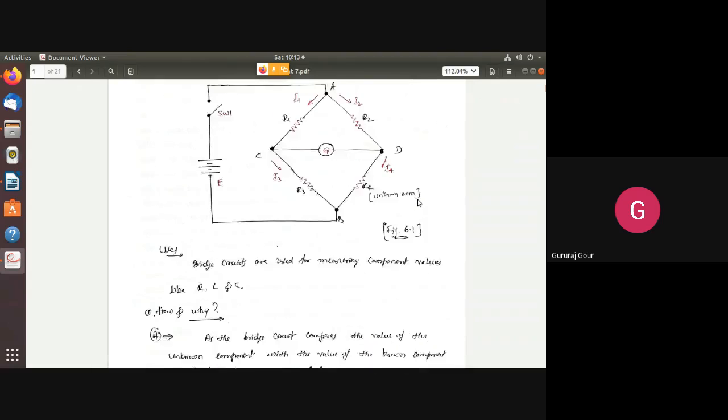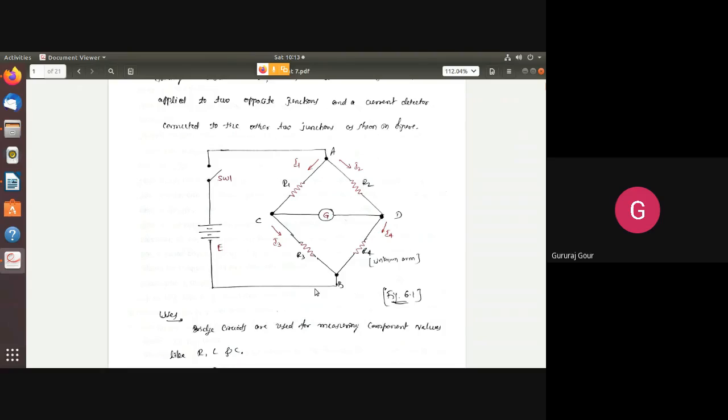The same circuitry I am using here. The figure shows a typical diagram for the Wheatstone bridge with the four resistive arms R1, R2, R3 as known resistances, with one of them variable, and R4 as unknown resistance. DC source E is connected in series with SW1. Before SW1 is closed, galvanometer G is properly calibrated with its null indication exactly in the middle.